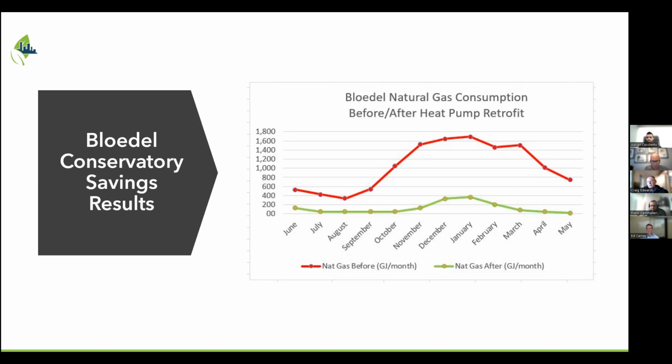And in that case with the police building, that provides most of the heating through the cooling coils, and then the building has a perimeter radiation system as well that's high temperature, which isn't served by the heat pump, and we put an electric boiler just to serve those high temperature heat loads in the winter, and that's a really successful project.